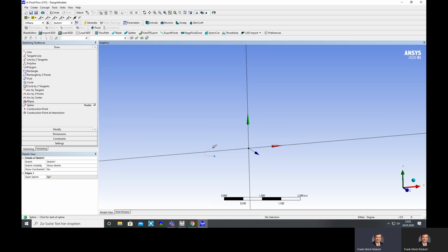Now you press on the spline with a small pencil. You press somewhere, but don't press directly at the axis. If you press directly on the green axis, the point will be caught by the line, and this is not so easy to unfix again.